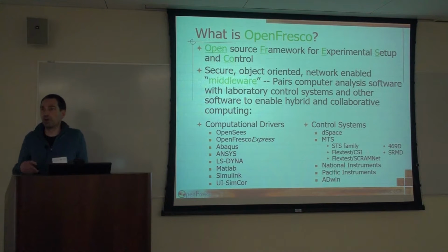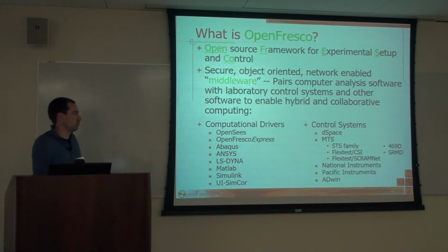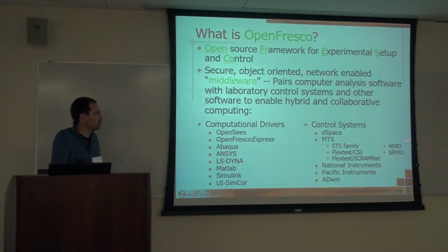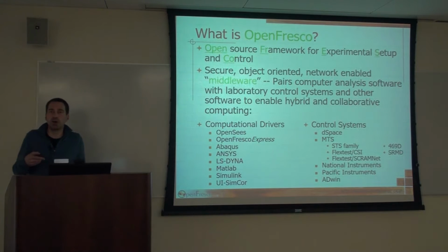The same thing is true on the other side of the test, right? In the laboratory itself, where the control system and the data acquisition systems are sitting, we have a lot of interfaces there too that OpenFresco can talk to. So we can talk to dSPACE digital signal processors, we can talk to the whole family of MTS systems there, so we can talk to the SDS family systems, we can talk to FlexTest, we've seen that through CSI, we can talk to FlexTest through SCRAMNet, we can talk to the shake table controller, the 469D, which we will actually talk a lot more about tomorrow, and we will see a demo of how we talk to that.